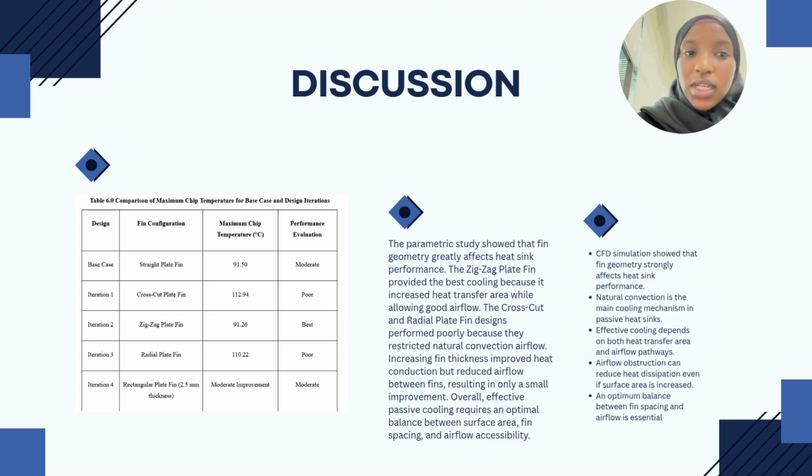The parametric study showed that the fin geometry greatly affected the heat sink performance, and that zigzag plate fin provided the best cooling because it increased heat transfer area while allowing good airflow. Also, the cross-cut and radial plate fin designs performed poorly because they restricted the natural convection airflow.